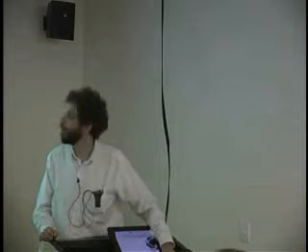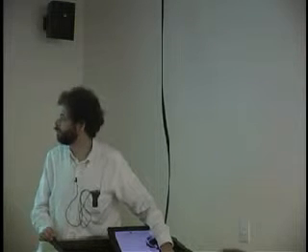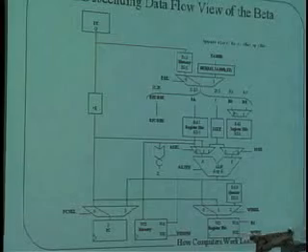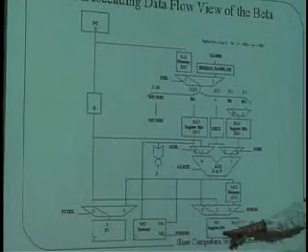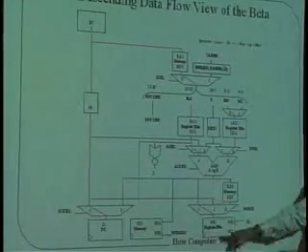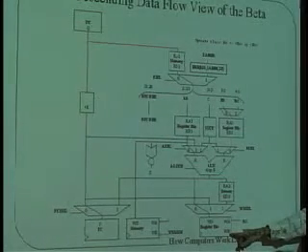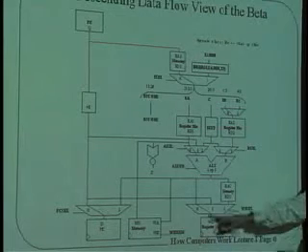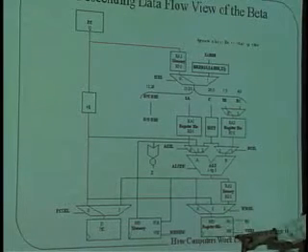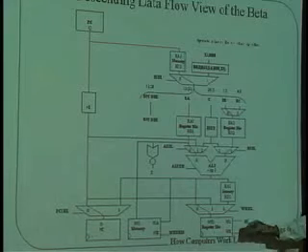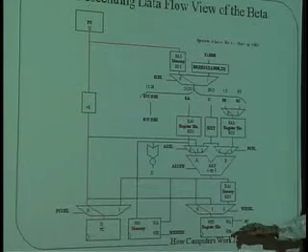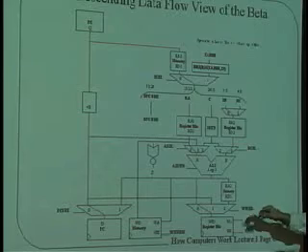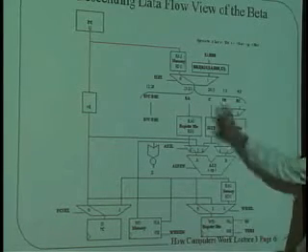Let me back up just a second here and show you the picture here. The E in this register file is actually called WE for write enable, okay? And when this is high, it says, when this clock goes off, take this data and write it. If this write enable was low, when the clock went off, it would do nothing, even if there was some new data here. So it's a way of disabling the action of a write when the clock goes from low to high.